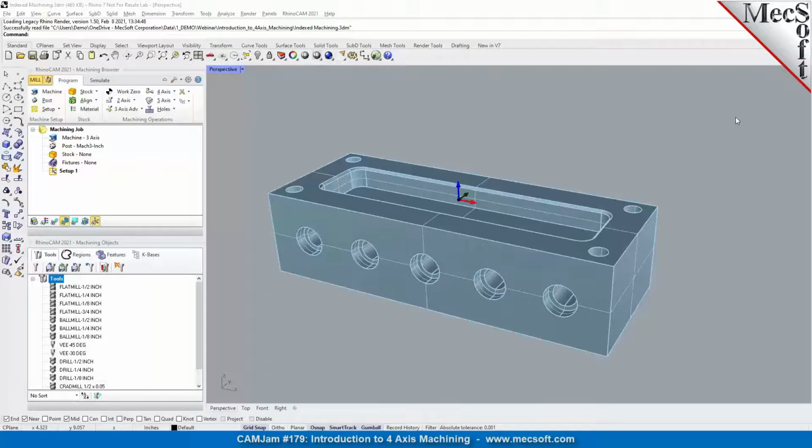Now, 4-axis, also known as multi-axis machining, is used for programming parts that require machining from one or more orientations. So considering a part has features that need to be machined from the top, from the sides, from the bottom, you would need to machine this in a rotary axis, where the part is typically held on a rotary chuck and it can rotate along the axis of rotation.